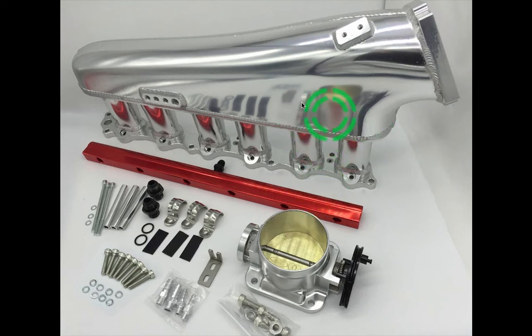So some other clever guys came up with the individual throttle bodies, which, I guess I don't have to explain, gets you rid of this. There's no tank, so no turbulence. Whichever cylinder, you have these throttle bodies, 6 of them with 6 cables, and then all hooked up to one source, which goes straight to your pedal.